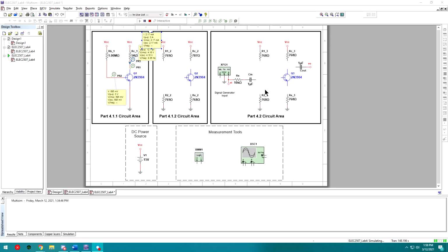14.315 microamps. So now, if I divide IC, 2.168 times 10 to the negative 3, divided by 14.315 times 10 to the negative 6, I'll find my actual value for beta for this transistor. And I'm calculating a beta that's around 151.44. So that's very, very close to what I calculated in the pre-lab, but as you can see, it's a little bit off from what we used.